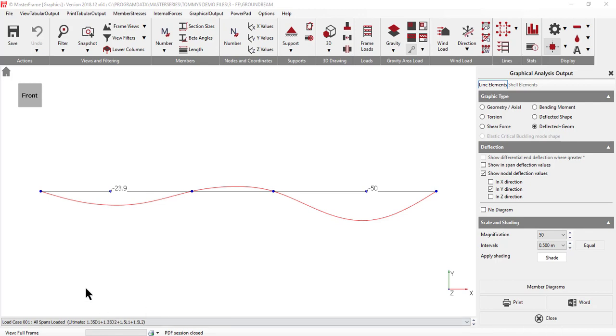Personally, I'd probably do it this way, split up into beams at 1 meter intervals and having the spring stiffness on each of them. And remember, if it's every meter, to put the two end ones as half the value, because you're only catching half the load and half the spring stiffness.